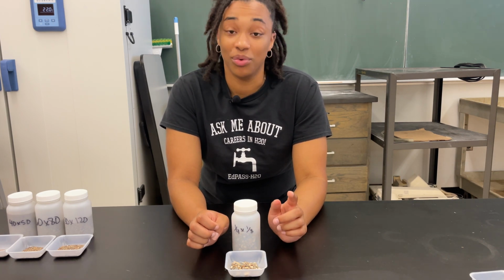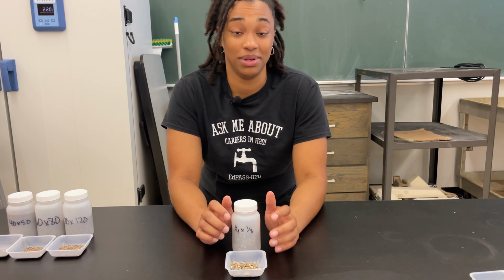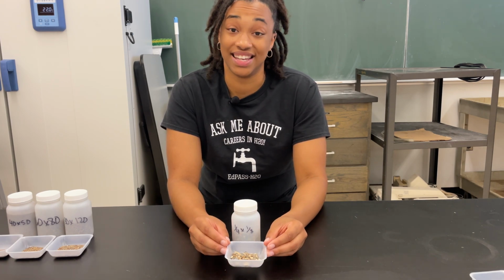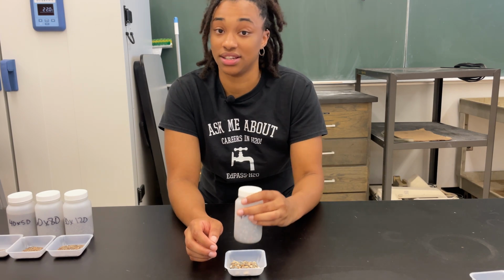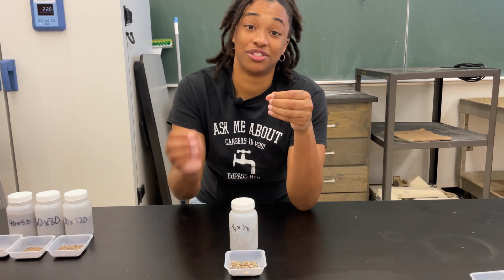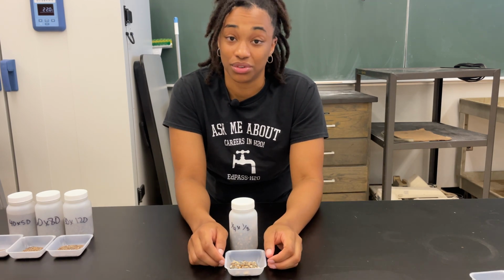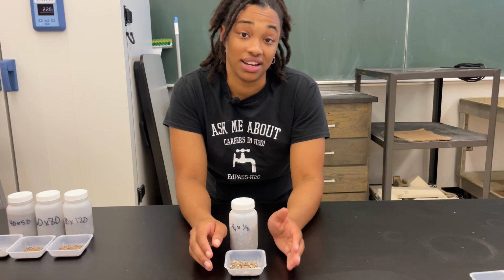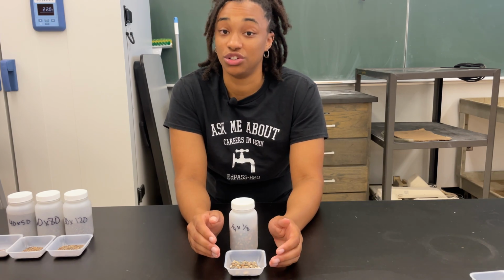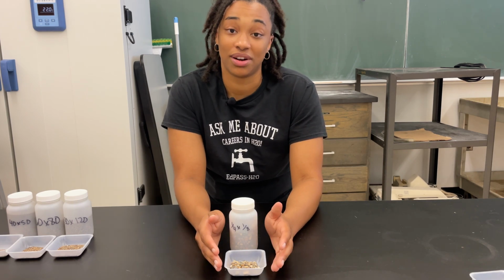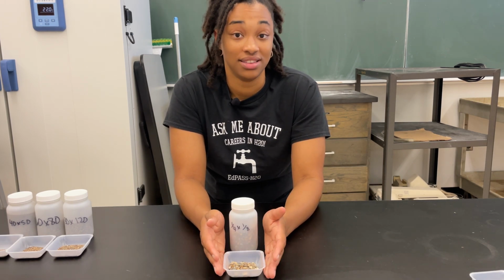However, it will not help filter out your smaller and medium-sized particles. The pore space that I mentioned before is getting larger the bigger the media size we go. And so if we have a bigger pore space, it can allow for smaller particles to filter through, unfortunately. This will negatively affect your turbidity. However, it does provide you with the fastest filter runtime. So you may need to choose wisely on how much you use this media.